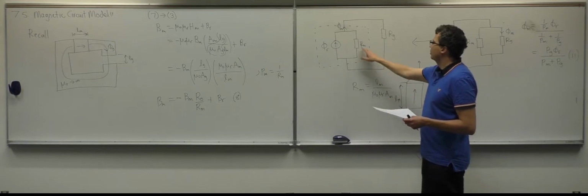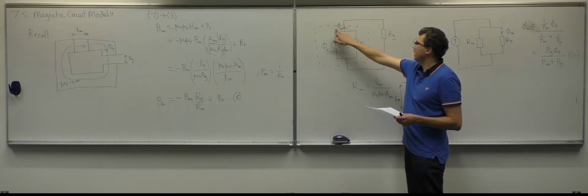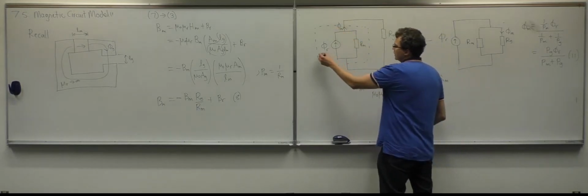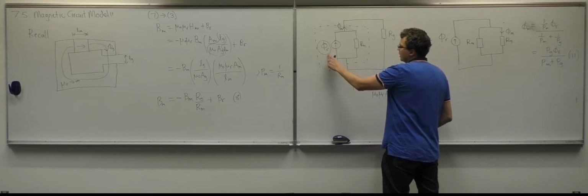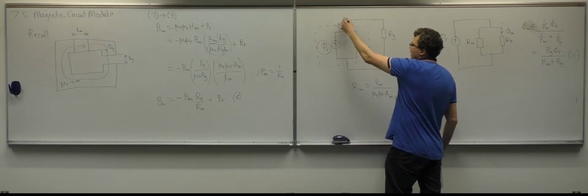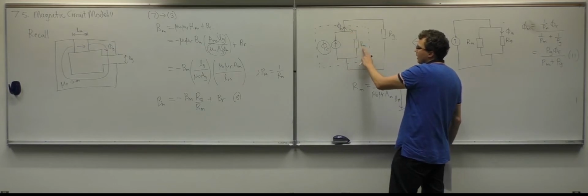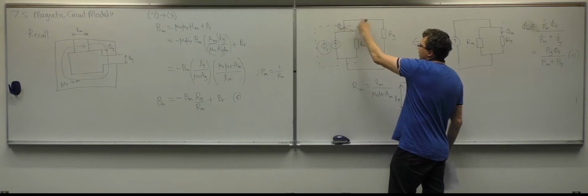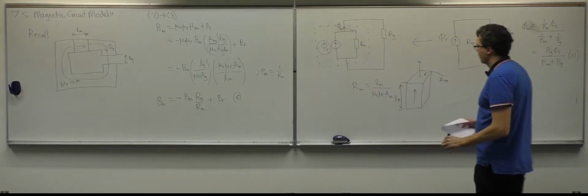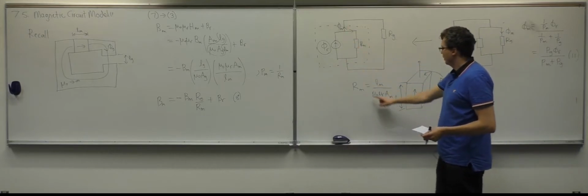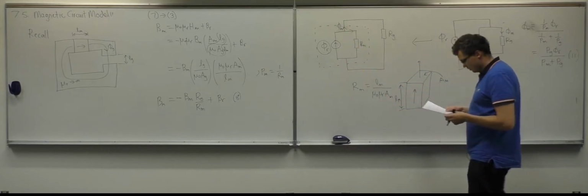So we are going to create the flux coming out. And then this here is from the source within the magnet, but not all of this flux gets out, because some of it's going to come back through the Rm term, and it's not going to go out into the air gap, right? And the amount that goes through is going to be dependent on the magnet reluctance term.